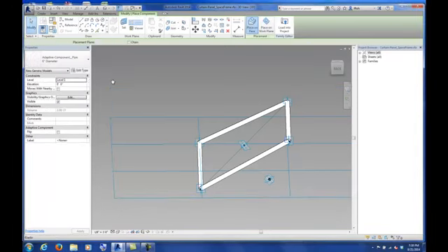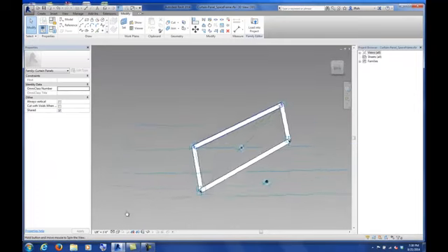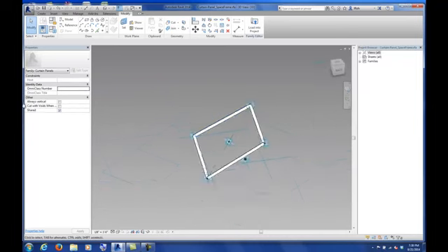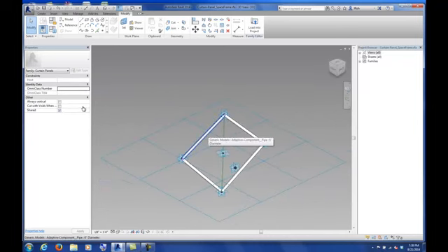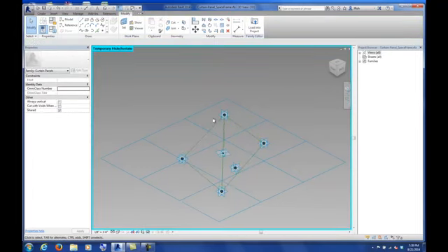Okay, and the last step here is to draw. We're going to draw with our 3-inch diameter pipe, but this time, to make this a lot easier, I'm going to select all of these pipes that we just created, and down at the very bottom of your screen, you should see a pair of eyeglasses. If you click on that, I'm going to click Hide Element. Basically what that does is it temporarily hides these things. From time to time when we get so much stuff on the screen, it makes it a lot easier to hide things as we move along.